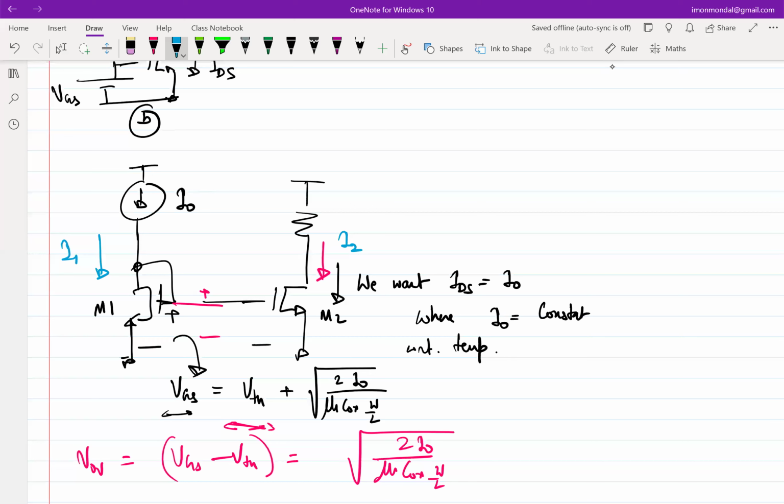I2 will always be equal to I1, because whatever is happening to the circuit on the left, the same thing is happening to the circuit on the right with regards to quiescent currents. Both of their VGS is the same because that's how they are physically connected. If the VGS is the same, and as long as we ensure the M2 on the right is in saturation, then the currents have to be identical. Correct? Does that answer your question?